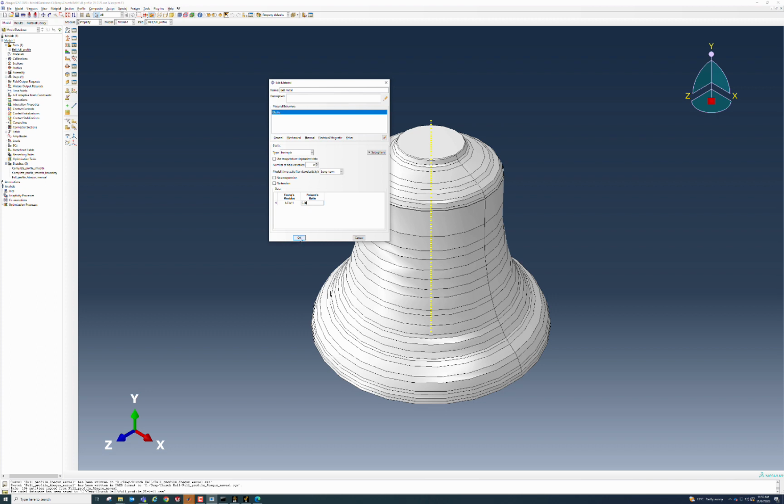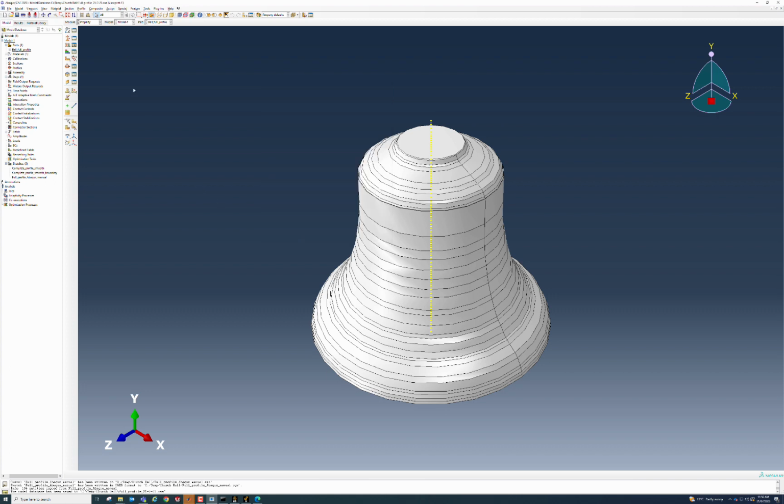That will allow the software to determine the deformation of the bell when subjected to a particular load, or in this case we'll ultimately be running an eigenvalue study, so we're looking to define some geometry and predict the natural frequencies, the resonant frequencies of this structure. The other property that we need as a minimum, although this isn't necessary for the stress analysis but is useful for determining the mass properties to ensure we've got the mass properties right, is the density.